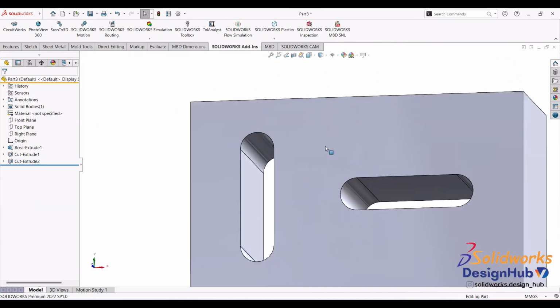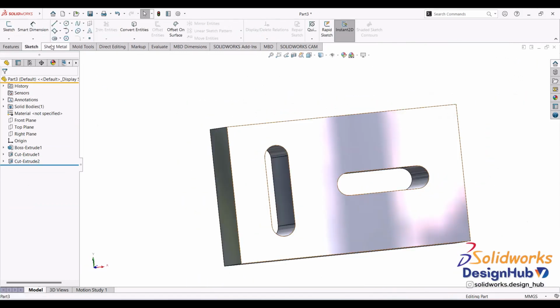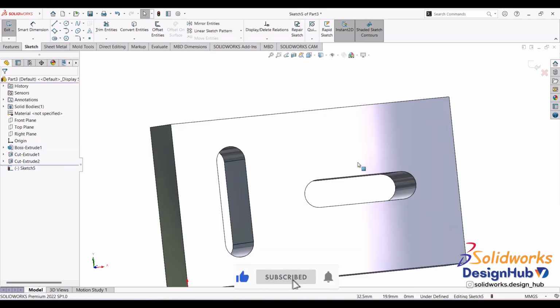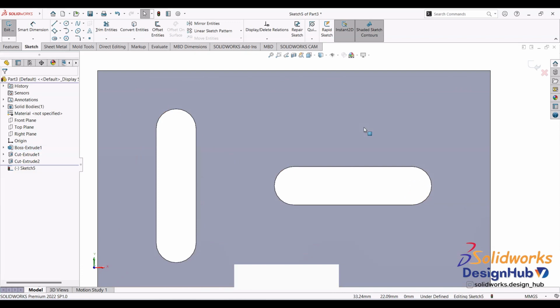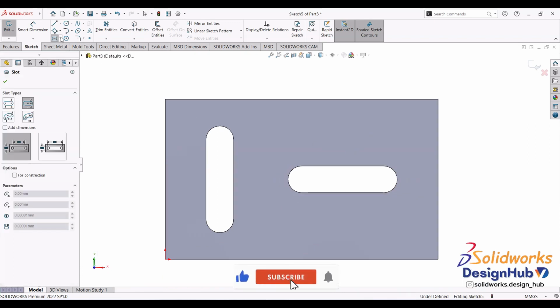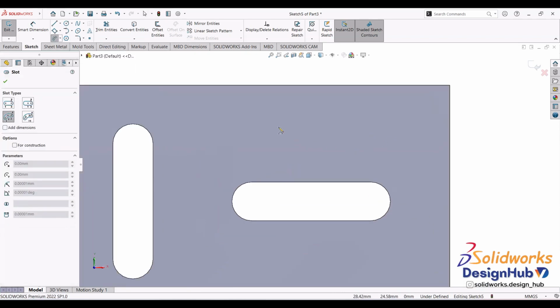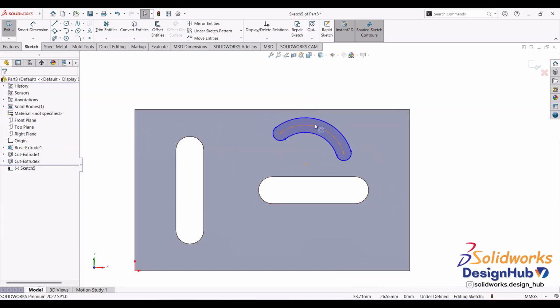Now the other tool is sketch in detail. You can see the 3-point arc slot. A circular sketch you can make by selecting a plane, selecting a face, pressing Ctrl 8 to get normal to it. Now I'll select a 3-point arc. I'll simply show here, will not go into much detail. You can do a circular cut like this, a circular slotted cut like this. That you can practice.